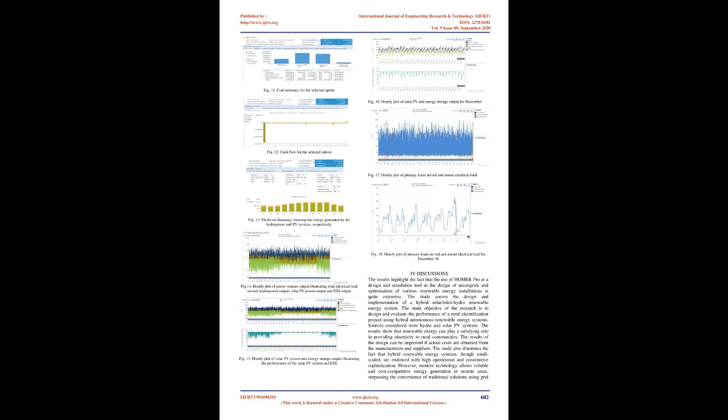The simulation serves two purposes. It determines firstly whether the system is feasible, that is being able to serve the electric load, and secondly, it estimates the life cycle cost of the system. The life cycle cost is represented by the total net present cost, which includes all costs and revenues that occur within the project lifetime with future cash flows discounted to the present. HOMER Pro's 1-hour time step is sufficiently small to capture the most important statistical aspects of the load and the intermittent renewable sources and equally appropriate to allow computation to the extent that optimization and sensitivity analysis can be handled.